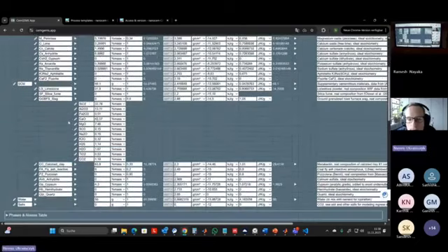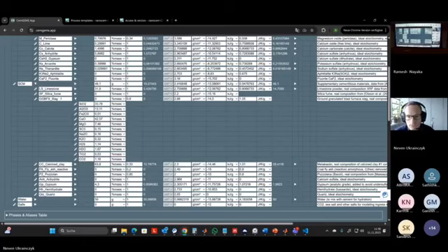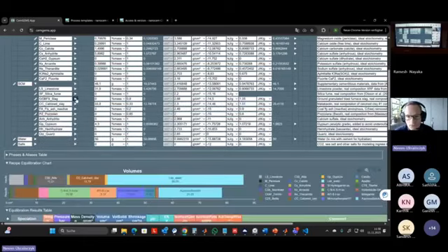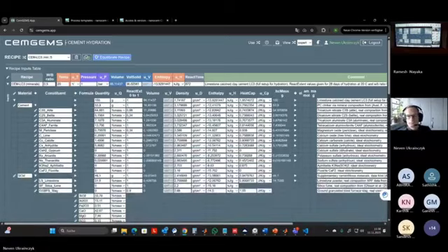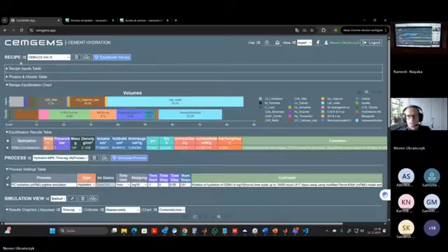It's only chemical composition. Yeah, but basically it's gamma C2S, which is not hydraulically active. Maybe there are some pozzolans inside that would react, but mostly I know that you need to activate the steel slag. Not so reactive.